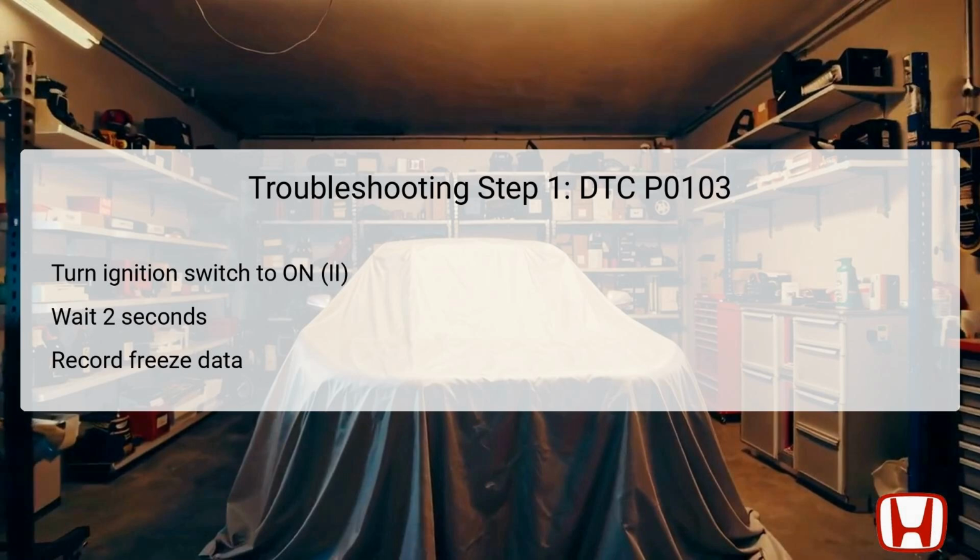During this time, it's important to take note of any freeze data and onboard snapshots that the vehicle's diagnostic system has recorded. Freeze data provides a snapshot of critical engine parameters at the time of the fault, which can be incredibly beneficial for identifying underlying issues. Additionally, reviewing any onboard snapshots might help outline what happened before the check engine light was activated.